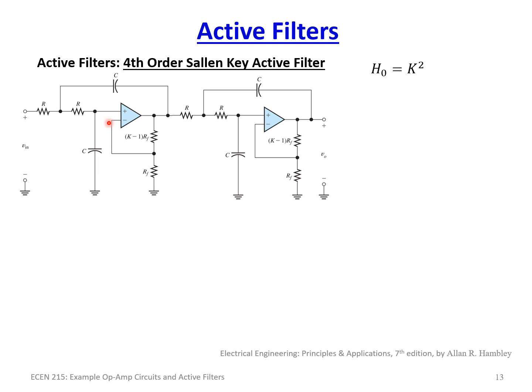The gain of one stage is multiplied by the gain of the next stage, and so on and so forth, as we were just seeing with the earlier examples. If both of these are identical circuits, all the components are at the same value, in other words, minus tolerance changes, then this has a DC gain of K, this has a DC gain of K, so you end up with K squared.